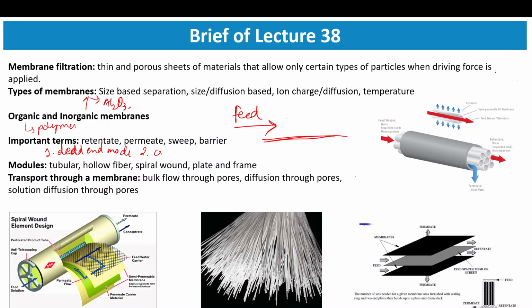Second is cross flow mode, which are very common. Now, out of these, cross flow is one of the most common because in dead end, you are entering the feed through this. Okay, so blockage of pores will be much higher.